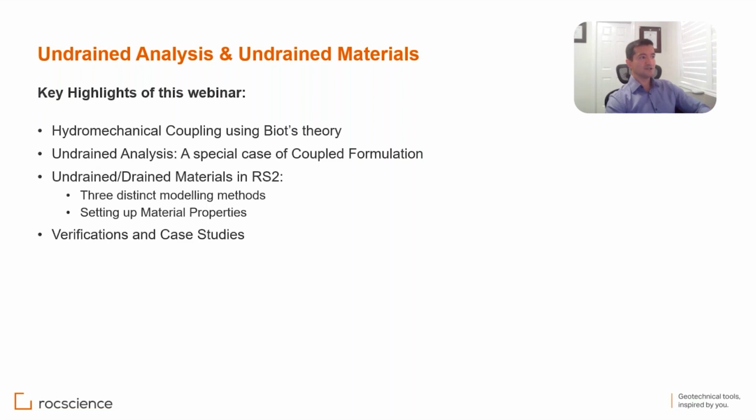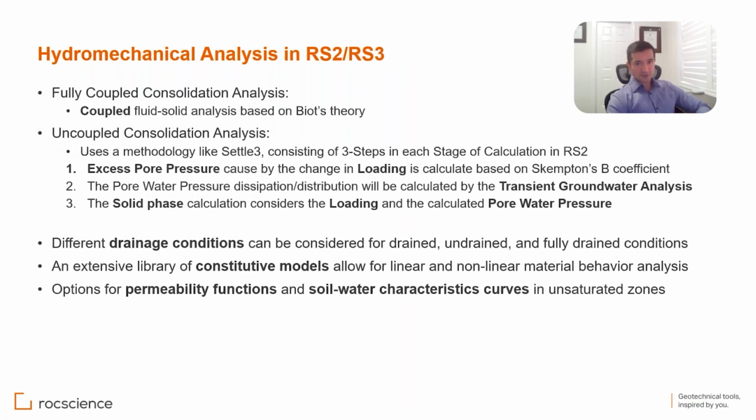We will start with the formulation first, the coupled formulation. In RS2 and RS3, for hydromechanical coupling, we have fully coupled consolidation analysis, which is based on the coupled solid-fluid analysis based on Biot theory, that u-p formulation that we have. I will present the formulation as well. On top of that, we have uncoupled consolidation analysis, a special kind of consolidation analysis that we can run in these tools, which is based on the methodology in our other tool, Settle3, and consists of 3 steps of analysis in each of the stages that we have in RS2.